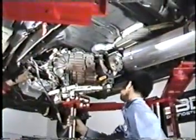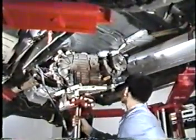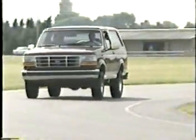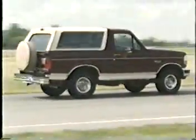Now, install the transfer case back in the vehicle and take it on a road test. It's shifting easily now, and it's not jumping out of gear. Replacing the high-low shift fork corrected the problem.